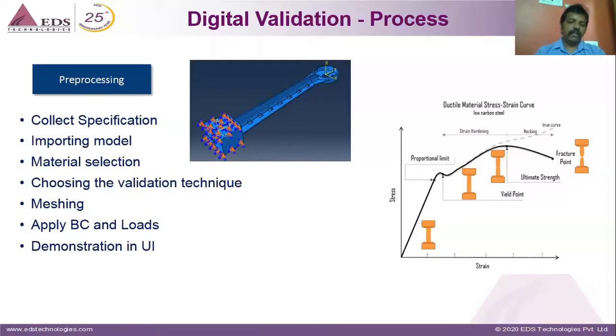So hereafter, the material property, the formula or the matrix and stiffness matrix, all those things, they sit on this mesh. It is based purely on the mesh, not on the 3D. Though it is a morph data, so meshing is very important. If you don't do a proper mesh, if you don't validate your mesh, or if you don't take care of convergence of mesh, then of course the result that you get will not be a proper result. So that is also very important.